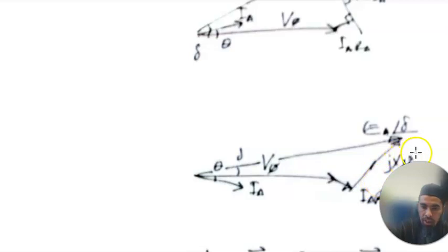This one I just exaggerate so that you have a guide on how to sketch the magnitude and angle of JXSIA, because the angle of your IARA is the same as the angle of your IA here. The angle of your JXSIA is 90 degrees compared to the angle of your IARA. So this is your guideline.